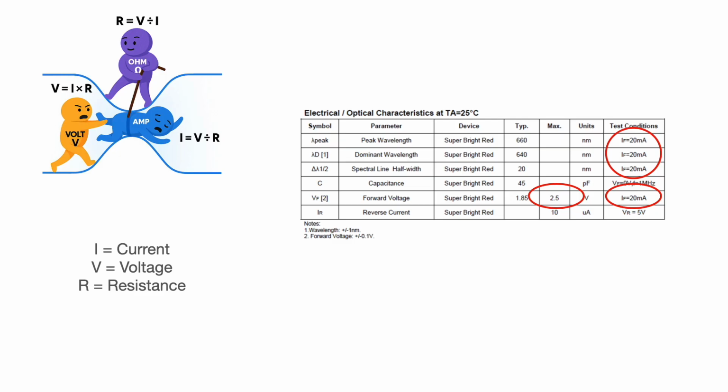Voltage forward is the amount of voltage used to activate the LED. That is all it does. So that voltage needs to be subtracted from the source voltage as it is not actually used to flow current. The current forward is the maximum amount of current we should allow to flow in a LED without compromising its integrity. Let's put that to work.